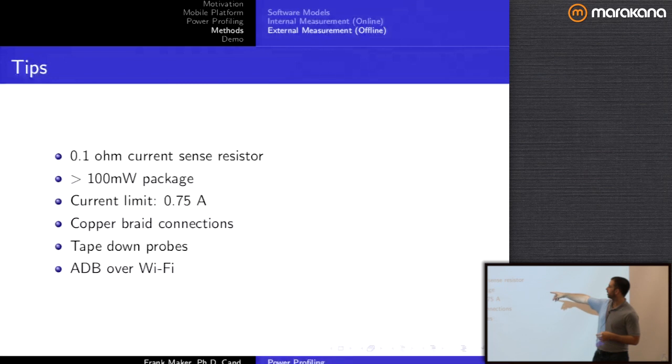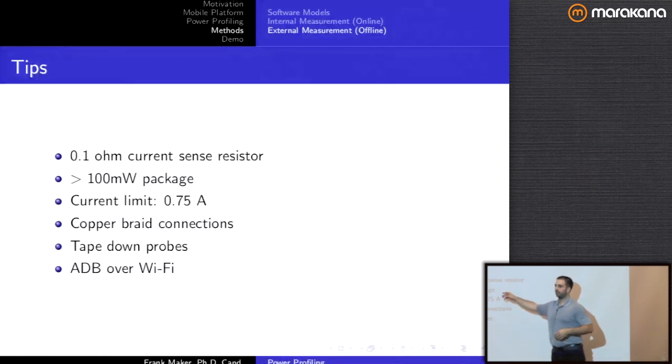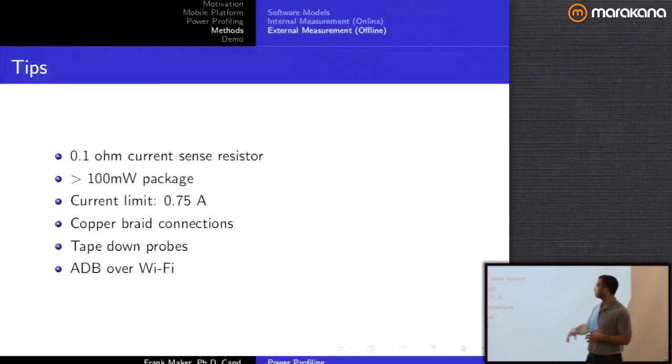The resistor itself, you're going to need a certain package, which is the name for the type of resistor, because there are all different types of resistors based on how much power they're designed to handle. You need one that's 100 milliwatts or more, roughly.